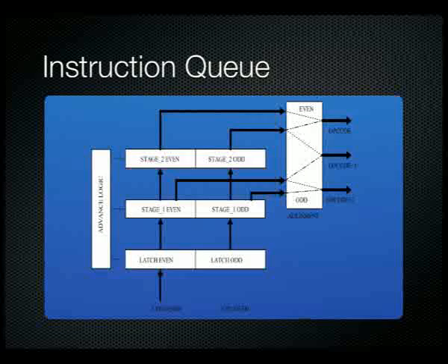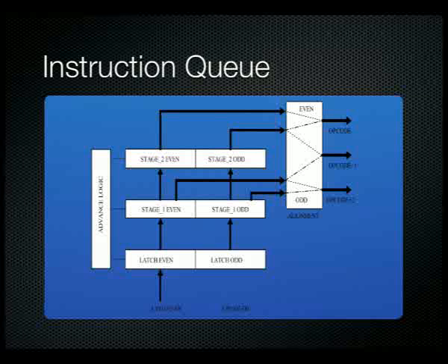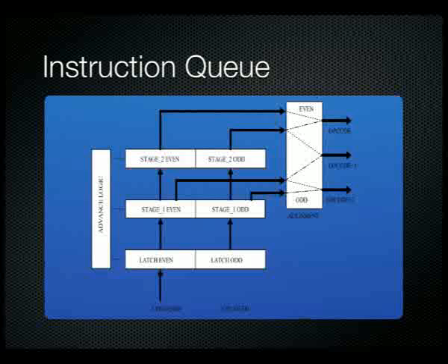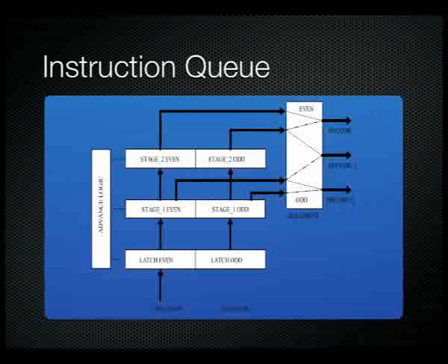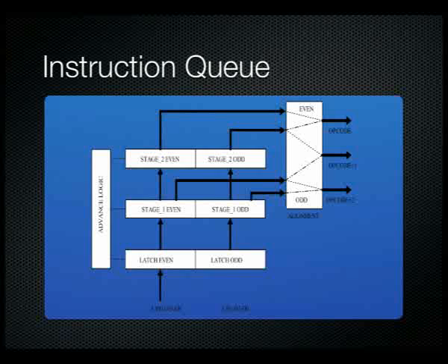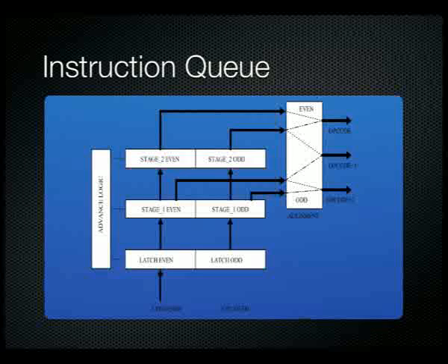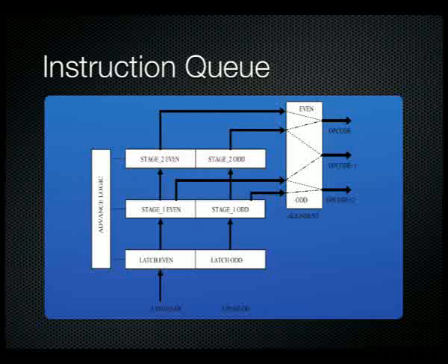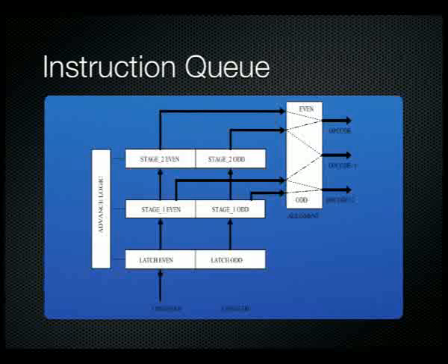When it comes to our processor of choice, we basically have a two-stage pipeline-like mechanism. If you go back to that previous diagram with the circular state machine, we actually have an independent section inside our processor whose sole responsibility is to fetch the next instruction, independent of the instruction decode and execute sections. This is what we refer to as our instruction queue. It continually grabs the next instruction and holds it in a buffer, ready for the instruction decoder and executor to deal with.